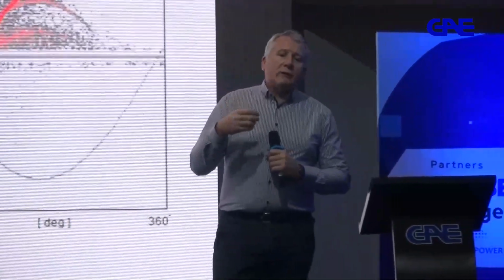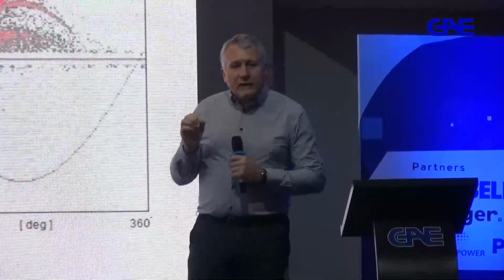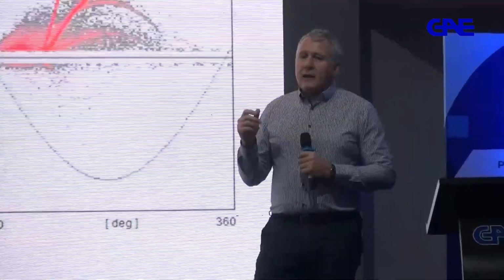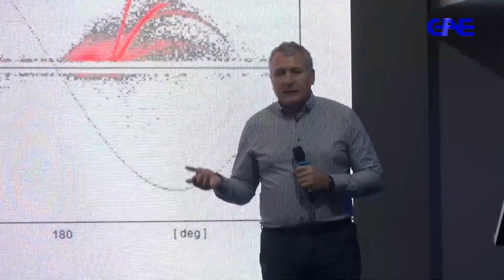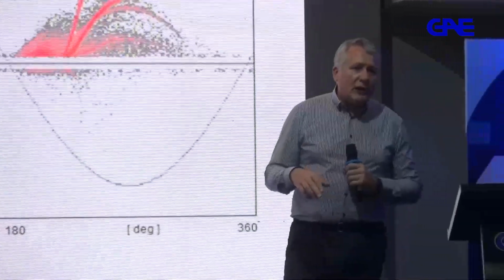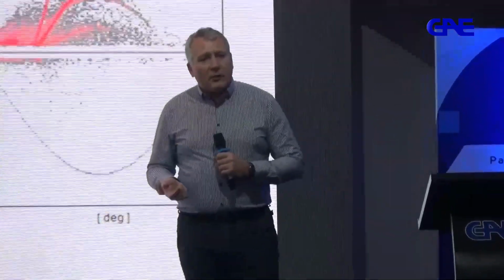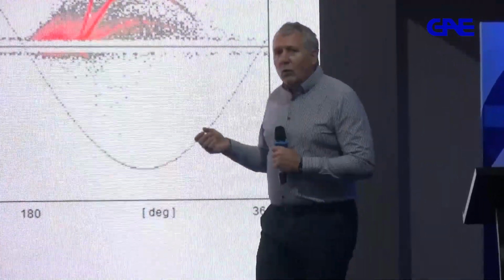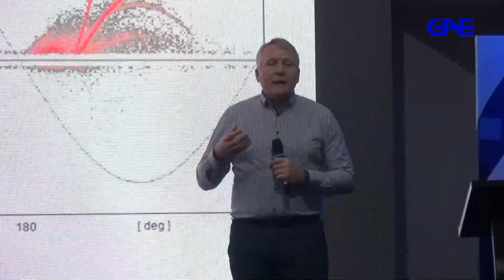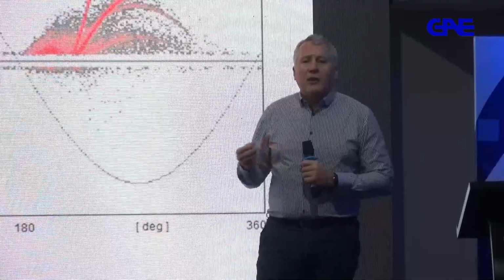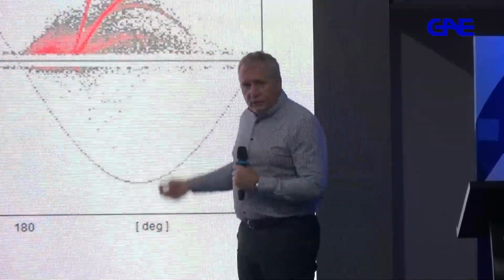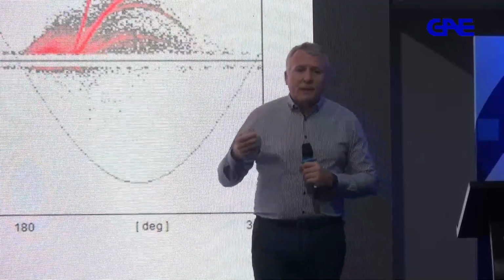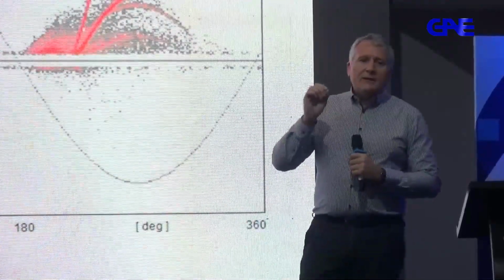So what I'm trying to convey to you is that for each insulator, be it what's happening inside of a transformer, inside of a GIS, for a rotating machine, or for a cable, all these assets, when they have insulation problems, do experience partial discharge, and for each type of asset, there is a signature.